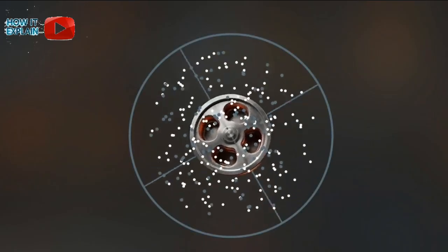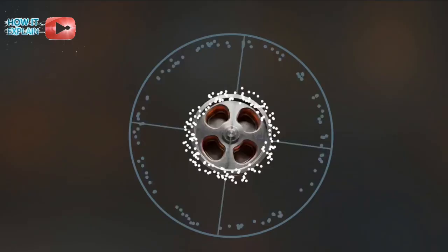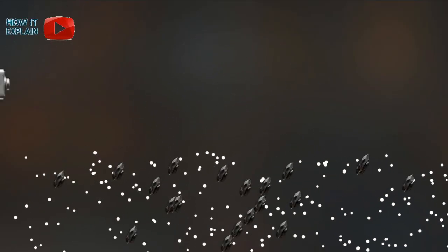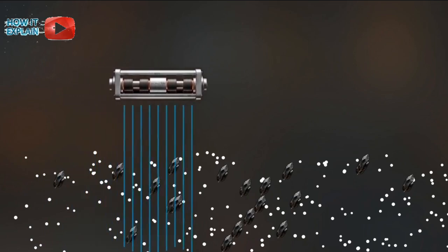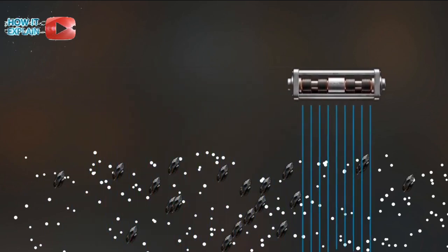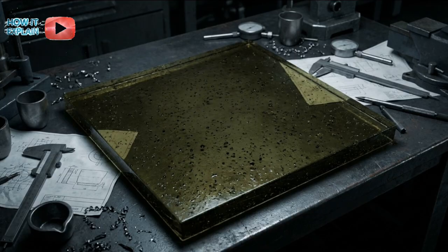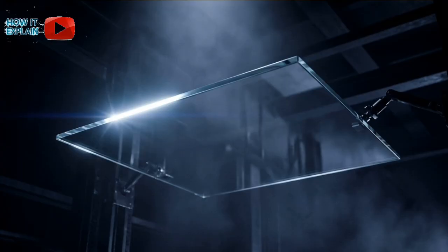Centrifugal force then separates out heavy metals that would weaken the glass. By spinning the mixture at high speeds, engineers pull the denser impurities away from the silica. A final magnetic field sweeps through the mixture to remove microscopic iron particles. If even a trace of iron remains, the glass will lose its perfect transparency, taking on a permanent green or brown tint. Achieving this level of purity ensures the final material is structurally sound and completely invisible to the eye.